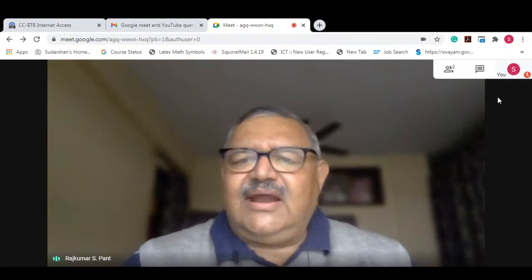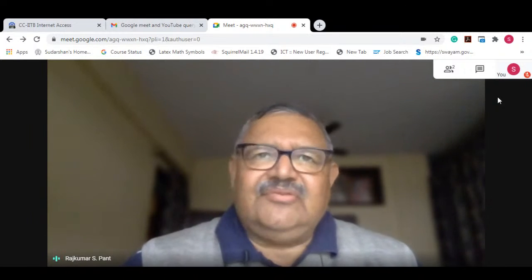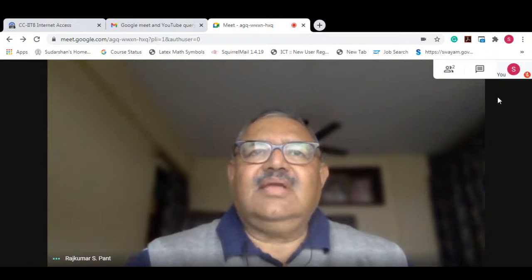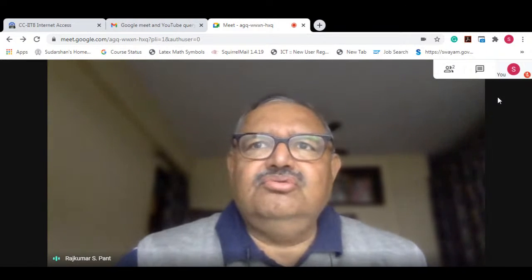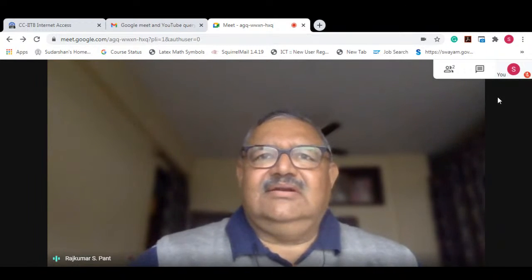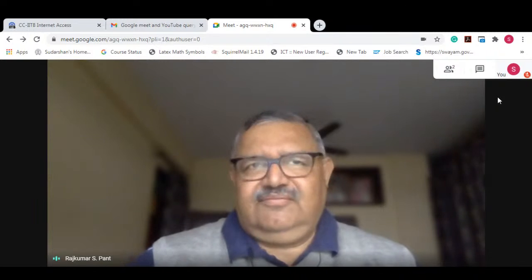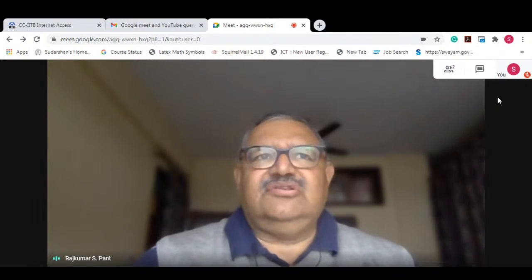Kshitij Gupta, I have already tried to explain about downwash. Induced drag, I already mentioned, and I repeat once again. As the aircraft flies through air, there is a tendency of the air at the tips to curl inwards in the form of thick, round vortices.